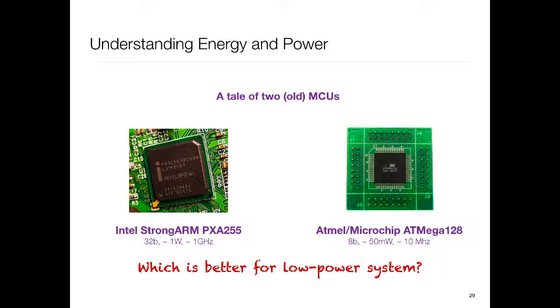And one has to be aware of this distinction, because oftentimes people mix up the two, and it depends upon what the objective is, right? As we saw earlier, I can have a low power system, but that may not be low energy, right? Because I can reduce the frequency arbitrarily to make it lower power, but then I'm just increasing the execution time, and therefore my battery will last equally long, right? It's not lowering the energy.